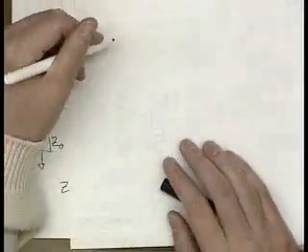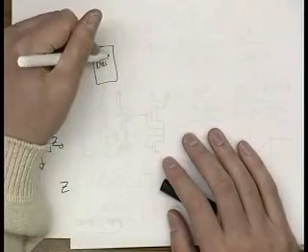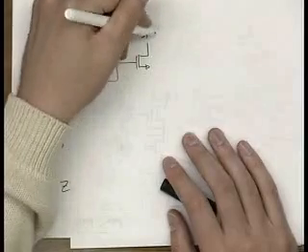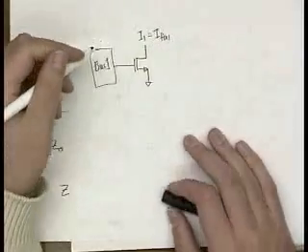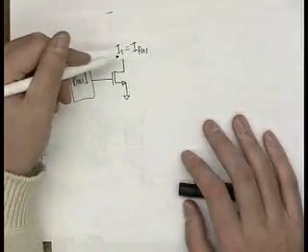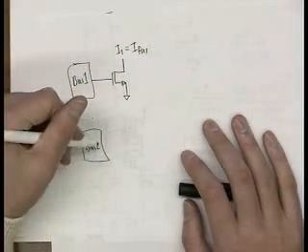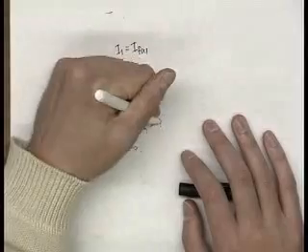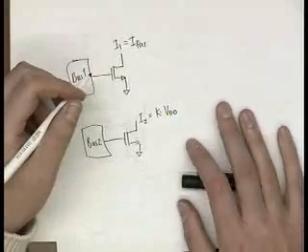And just one final note. So let's assume you create your bias structures. So bias 1, I1 is equal to Ifix1. So I1 is totally independent of supply. It's just a fixed current. And you also have a bias 2. Now let's say I2 is equal to K, some constant, times VDD. So it's totally proportional to supply.